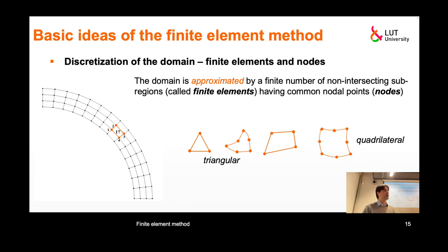That refers usually to how the known function is interpolated, and we will talk about that very soon, but it also refers to their shape. So their shape might be with linear edges, and it might be with quadratic edges. Might be something else, but those are the two most commonly used. So this is how it would look for a triangle element with nonlinear boundaries, and this is how it would look for a quadrilateral element with nonlinear boundaries.